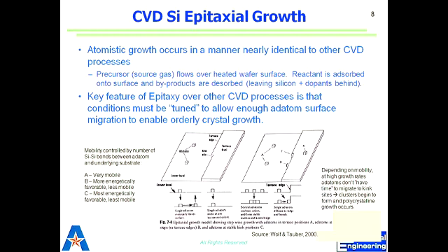So how does it progress? Just like CVD, we have these products of reaction which get to the substrate, and then once they get absorbed, they travel. They find what we call a terrace. So this is a terrace which is growing. They get to the edge and start adding to the growth of the terrace.